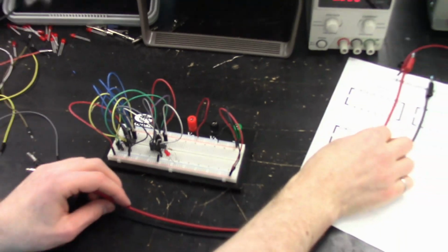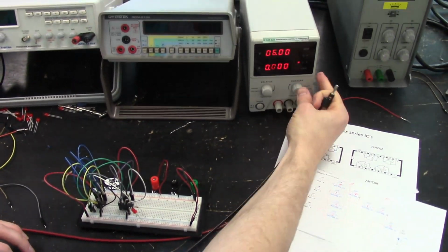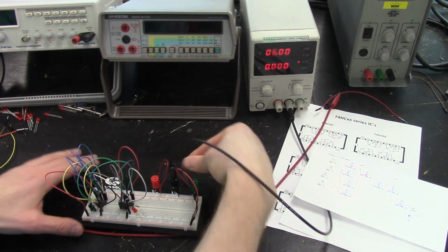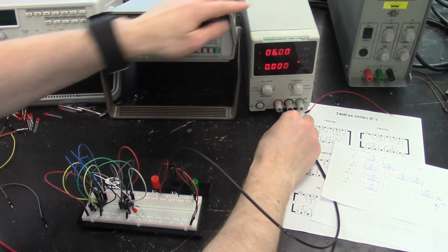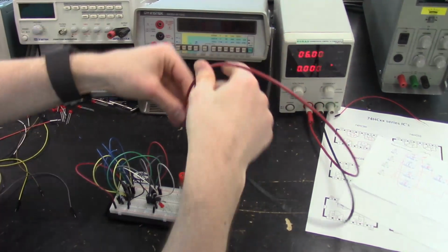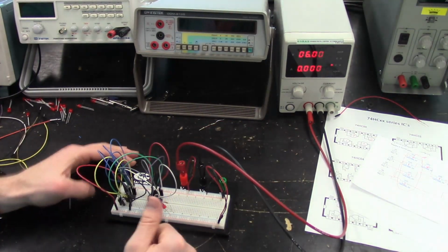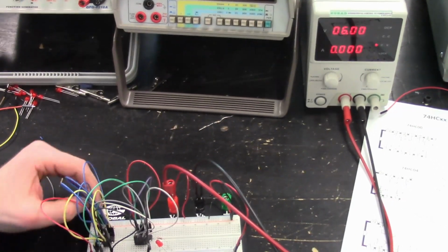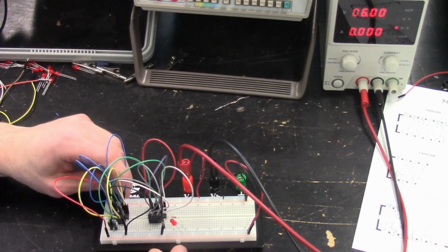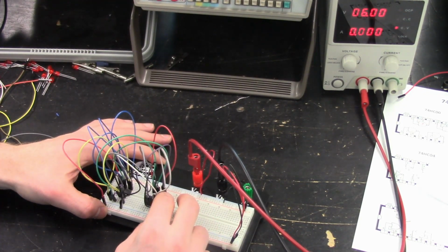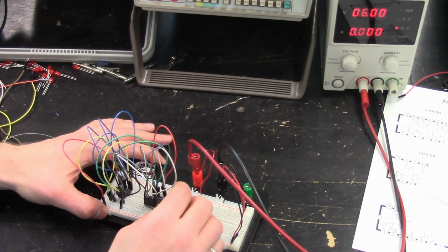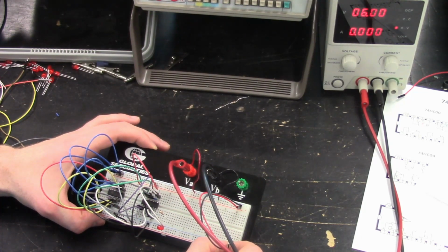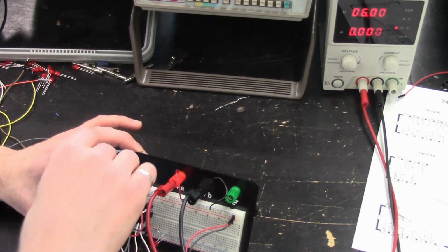So we've checked already that the circuit is set to 6 volts and has a reasonable current limit. So we'll wire up the lows and the high. Okay, now we'll put this to a logic that should give us a prime. So if we were to connect pin number D here to high, then the output pin should go high if we haven't wired anything up wrong. And then very unfortunately, it has not. So alas, this means something is miswired on our circuit.